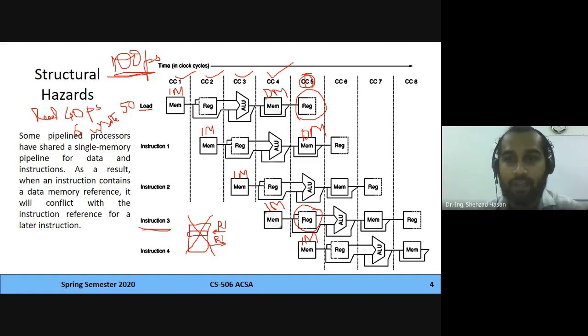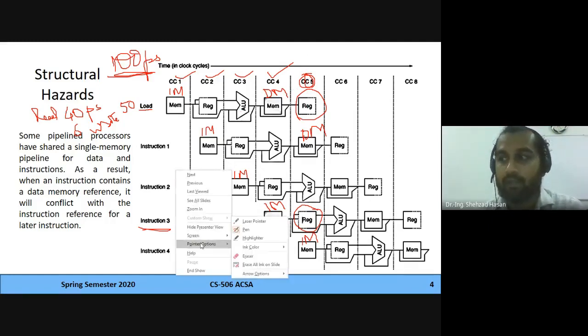Now this is a different way than what we did in the memory, because if our cycle time is 100 picoseconds and memory is taking something like 100 picoseconds, then we cannot have two different operations in the same cycle. But for registers which are taking less time, we can have two different register operations happening at different times in the same cycle. So a way out for that is to divide that cycle into two halves, and then you can manage which operations should happen first, right?